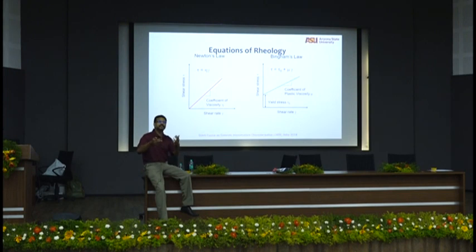When it gets to a certain critical energy, you start to flow. Fracture of glass, fracture of brittle material, same thing. You get to a critical fracture length, a critical length beyond which glass will immediately fracture, right? Brittle materials will immediately fracture. So again, an activation energy concept where you have to give it certain energy beyond which it will flow well.